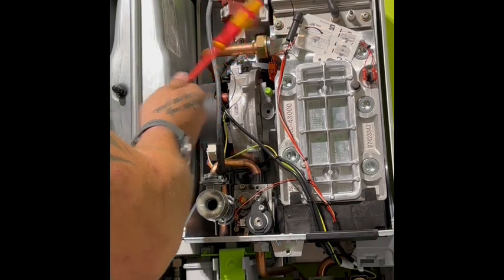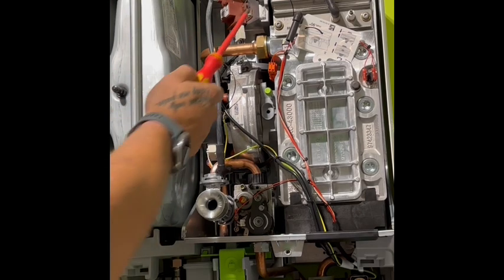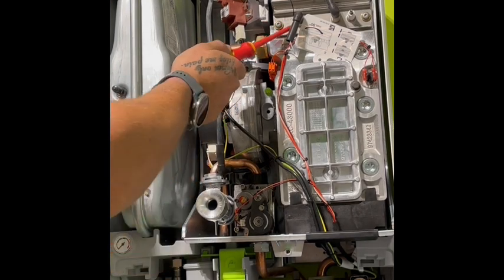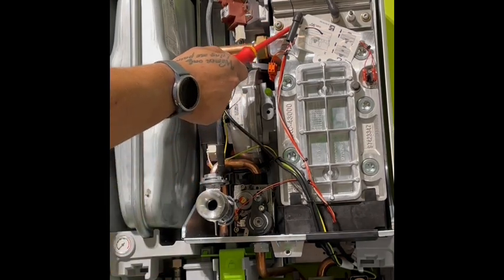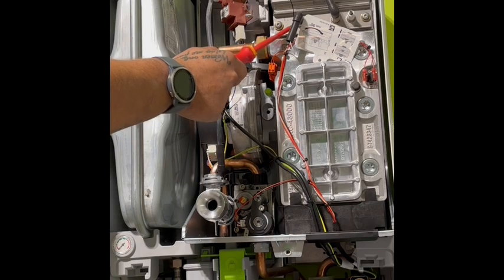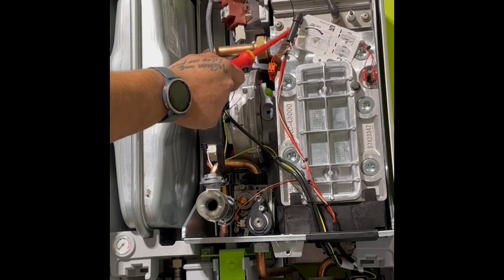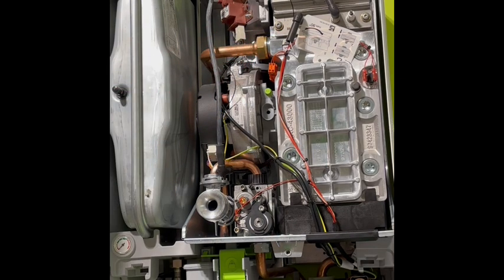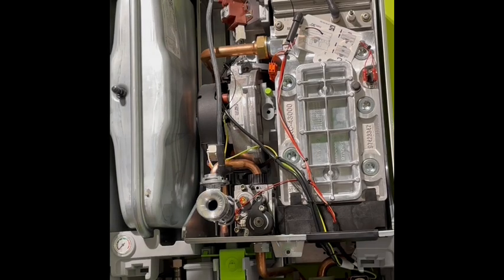One thing to note on nearly every boiler, if you're taking an electrode out, at the back of that there's going to be a gasket. That gasket can need replacing, so you're going to have to bear that in mind when you're taking stuff out. Is it safe when you're putting it back in? Have you replaced the gaskets?